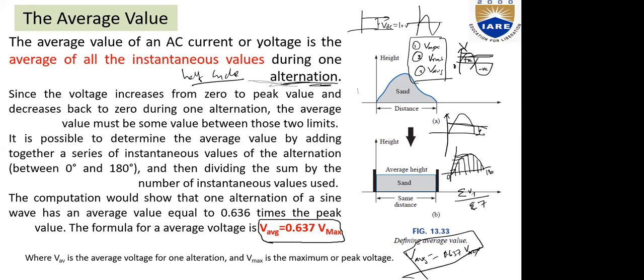You just take the calculation and do it, right? Suppose you take a sinusoidal waveform and assume some magnitudes on that. Yeah, you will get 2 V maximum by pi. What's the value of the result? That is 0.637. Yeah, both are the same, right? For I naught also we will get the same, because they are in phase. We do the same calculation for I average. I naught sin omega t or V naught sin omega t, V and I are changing, both are the same. Yes, fine.